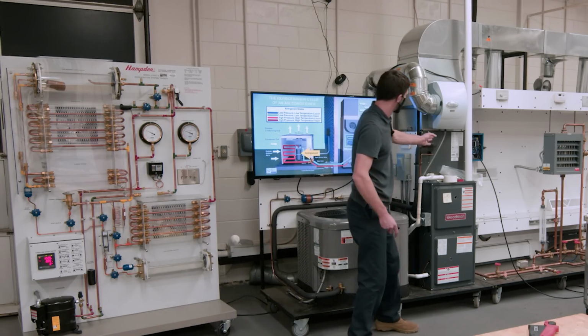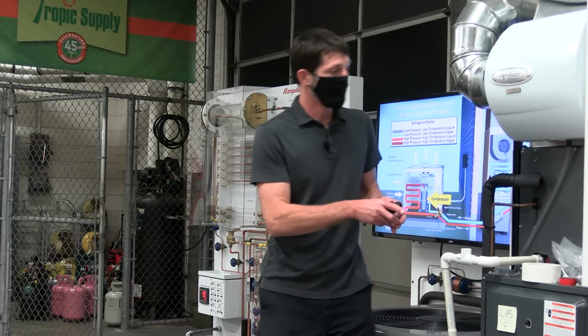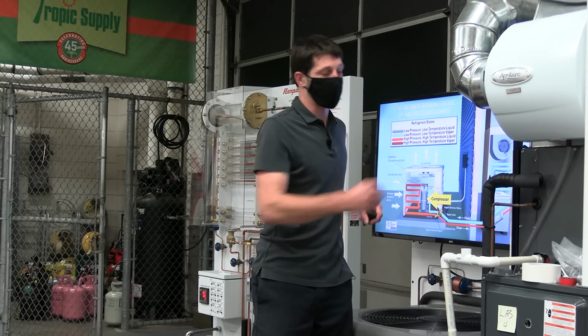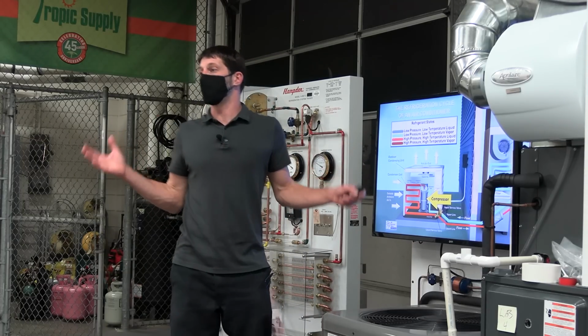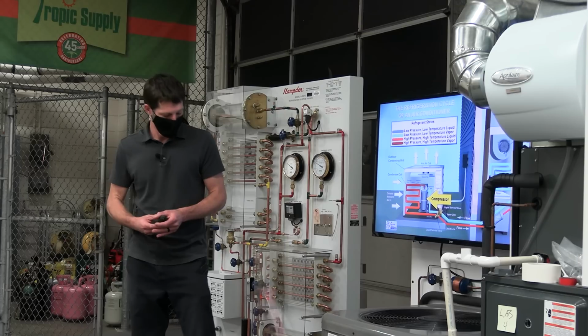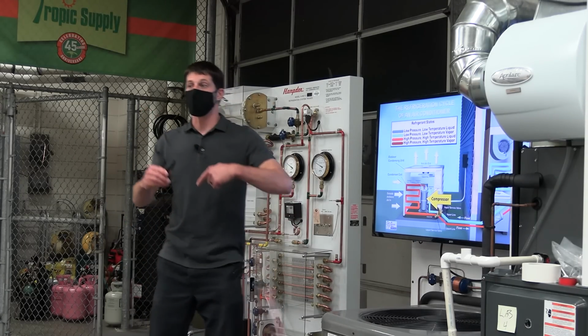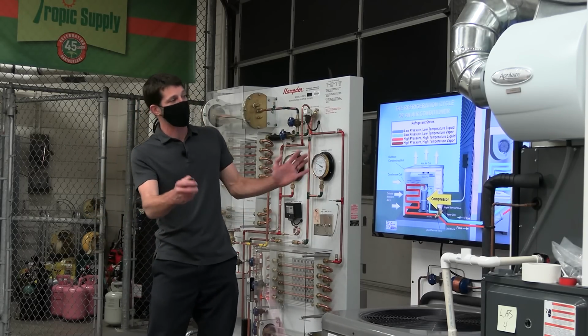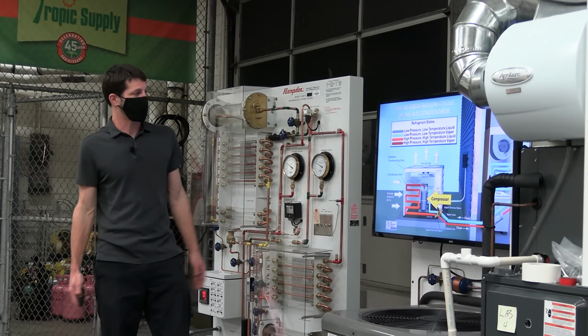Same thing in your evaporator coil, you'd have to take the evaporator coil cover off and find where you believe the saturated state is going to be and put a temp probe. That's why we don't do that. Very time consuming, there's a chance for error there. We check the pressure and convert it immediately to saturated temperature. But the whole point is that we're operating based on temperatures.